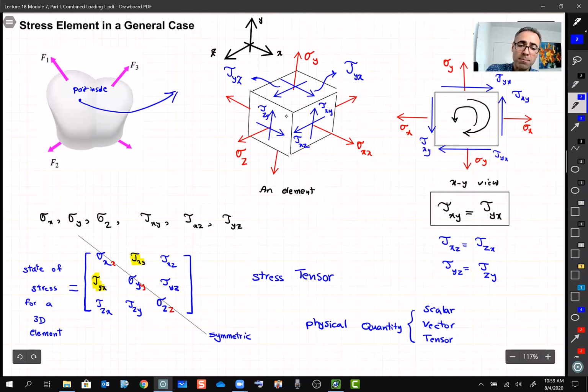Or you are on a plane whose normal axis is the z-axis. You need to tell people which plane you are on. And this is a quantity which we call a tensor, and stress is in the category of tensors, basically. But so far we didn't talk about tensors, because all the cases we studied were simple cases. We showed it more like a vector, more like a direction. But from now on, you learn that stress is a tensor.